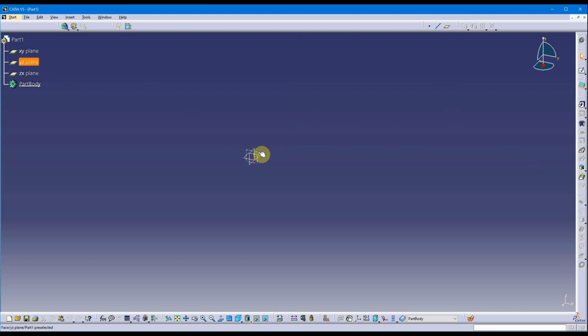So what can you sketch on in CATIA? That's a good question to ask before I begin here. In CATIA, you can sketch on really any reference plane, any flat part surface, or plane of an axis system. Those are three things that make for valid entities that you can sketch on. The most obvious thing I have available right now is one of my three default reference planes.